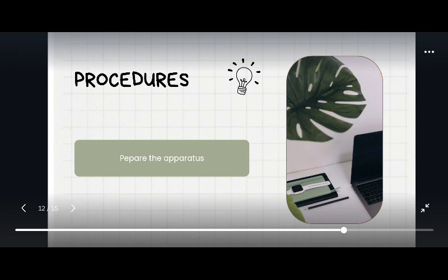One of the trials shall be for a closure requiring 30 to 40 drops, one for closure between 20 and 29, and one trial for a closure requiring 10 to 19 drops. Determine the water content from each trial by using the same method used in the first laboratory. Remember to use the same balance for all weighing.